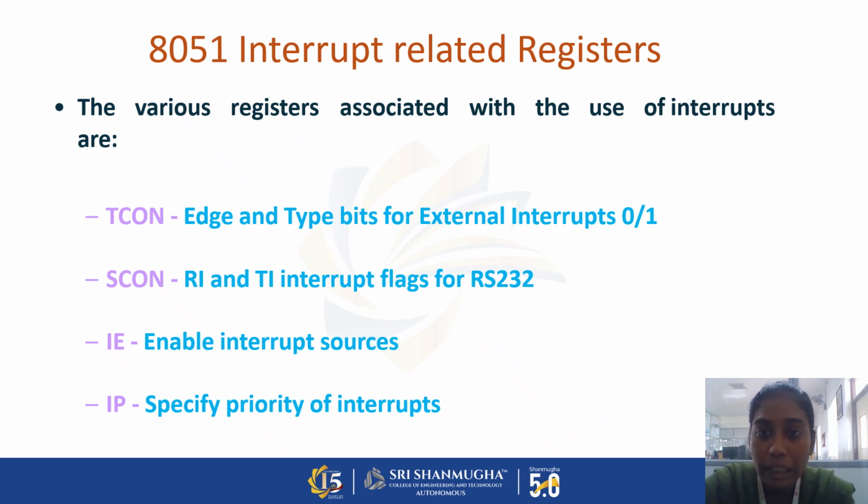Now the 8051 interrupt related registers. The registers used specifically for interrupts are the TCON register, SCON register, IE register and IP register. The TCON register mainly focuses on the external interrupts and the timers. TCON means timer control register.